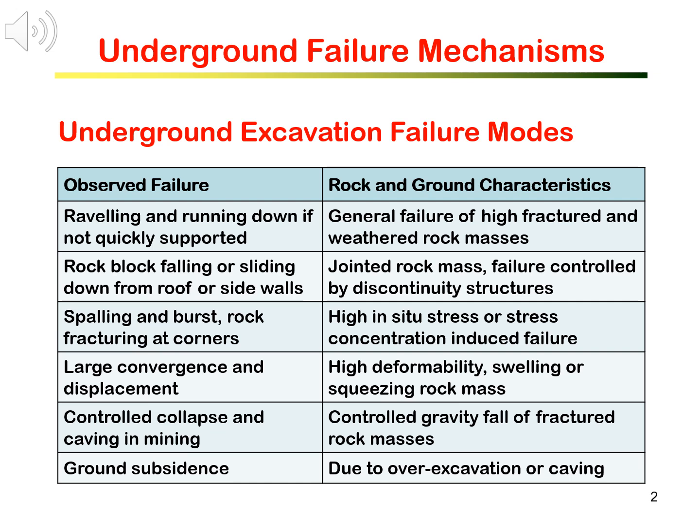3. Spalling and rock burst at excavation's face, and rock fracturing at the corners due to high stress or stress concentration. 4. Large convergence and deformation, when the surrounding rock is highly deformable and swelling.